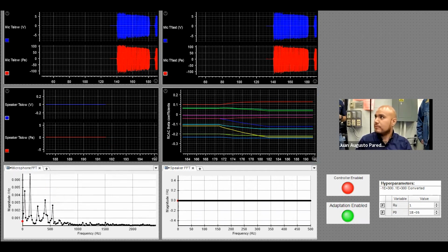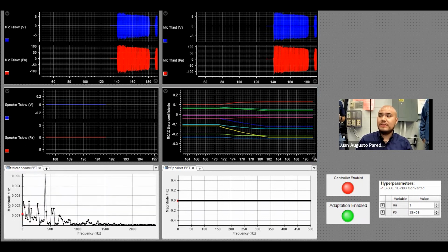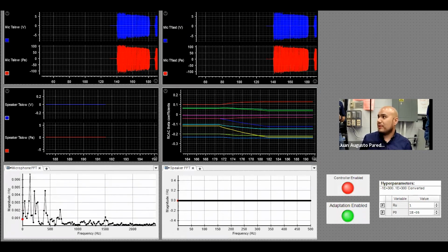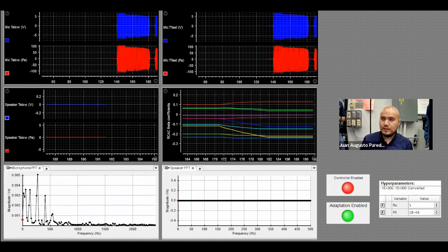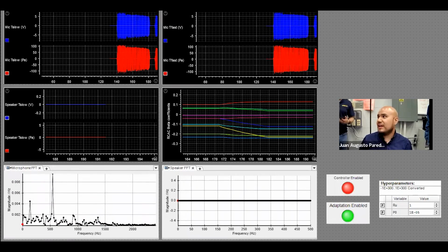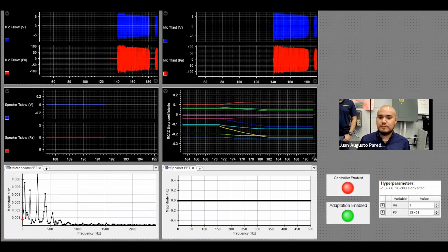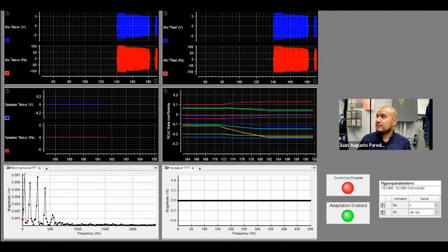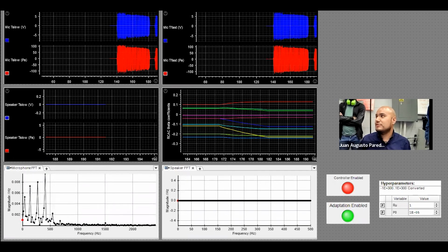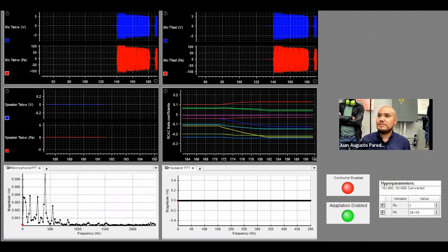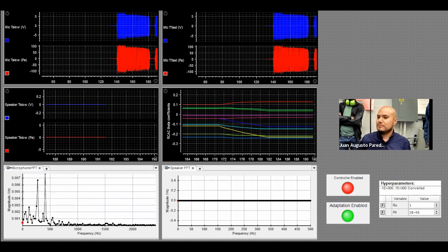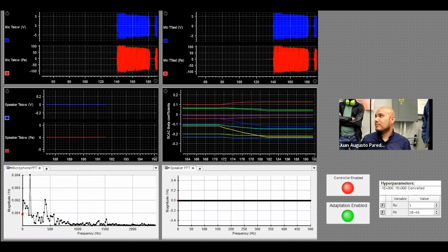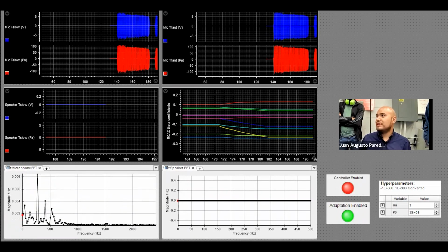Do you always use the same number of coefficients? Like I said in the previous presentation, I chose the number of coefficients because at that sampling rate, I covered most of the waveform. And in all of these tests, I have used the same number of coefficients. Would you expect the performance to be diminished if you use fewer coefficients? Yes. That being said, increasing the number of coefficients usually has no bearing on performance. The only issue is that it also increases the amount of computational effort that your computer needs to do. So if you increase the control coefficients too much, you may not be able to run it as fast as you can. Sure.